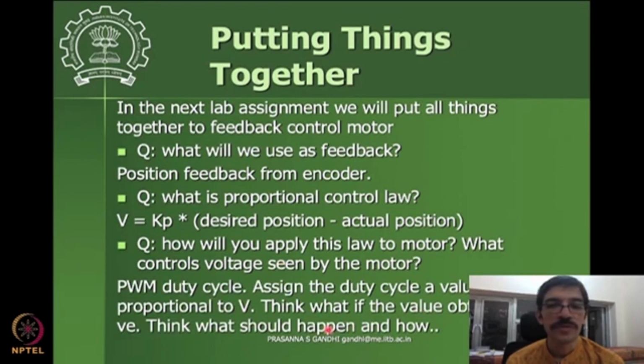So that's what we are discussing. What if this value is negative? We need to use the IN A and IN B pins of the driver to reverse and change the direction of the motion.